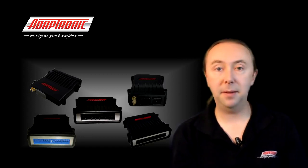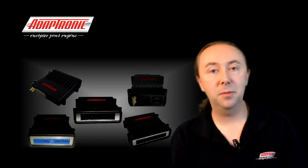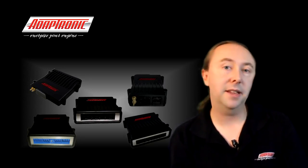Now, TurboSmart have actually come out with a solution to this, which is called the IWG. It's basically an aftermarket replacement for an actuator from an internal wastegate type turbocharger, and this differs from the factory one because it has a much larger diaphragm area, which means that the boost regulation is better because it has more ability to overcome the force from the exhaust back pressure pushing the wastegate open. So this makes the boost pressure more consistent and more predictable, and also increases the maximum amount of boost that you can run with this configuration.